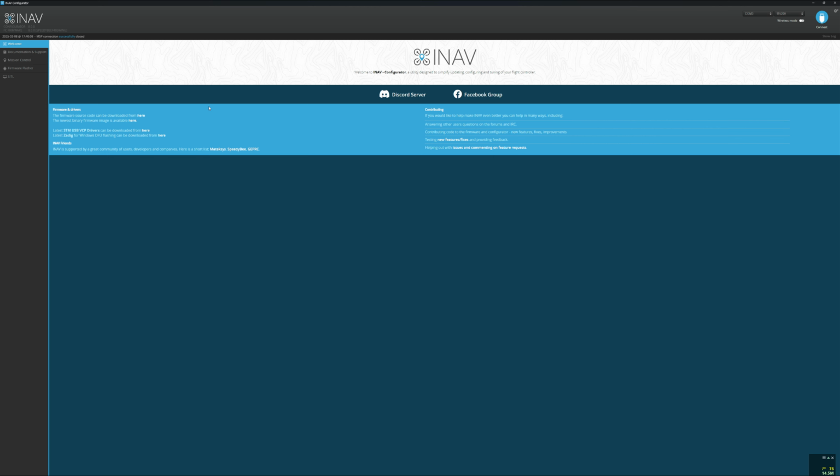So one thing you may want to do, if you are on Windows, is go through and install the STM USB VCP drivers. You will have to log into STM's website, kind of a pain, but once you're done, you don't have to deal with it anymore. And then the Zadig for Windows DFU flashing, make sure you grab that one as well, because we will need that one here in a few seconds.